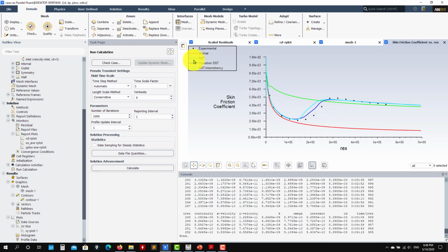Then running purely SST, fully turbulent, you have it fit to the turbulent solution. And then we are using two other transitional turbulence models, and see that they managed to capture that transition to turbulence. So what I was saying is that it's very elusive and very difficult to capture.